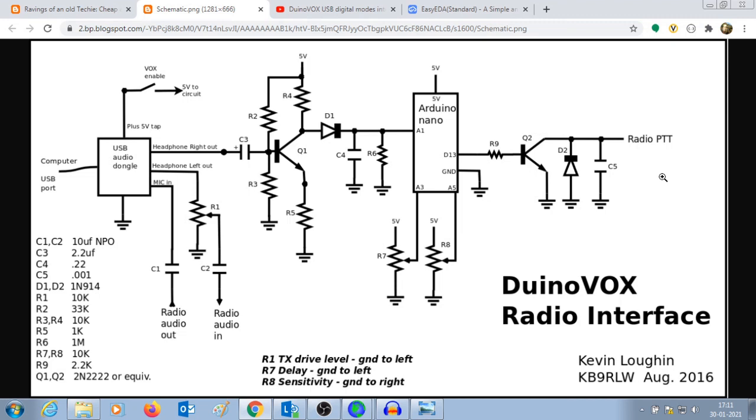So this can be useful if you want to control the radio using CAT communication. So you will require another USB cable running between the laptop and the radio, and the PTT can be triggered over CAT. So if you want to use it that way, then you can switch off this switch, and then the WSJT-X will control the PTT of the radio over CAT.